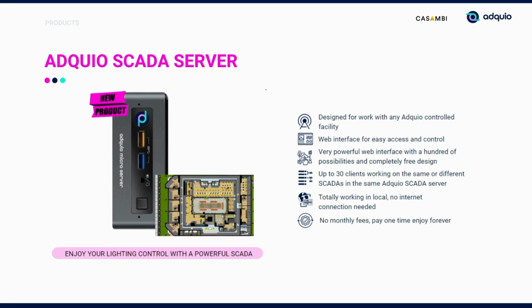You can use the pre-designed objects that the SCADA itself already incorporates, such as buttons and sliders, and connect them to the variables of your controller. And from the screen, you can then modify values in real time of your installation. In this way, we have two types of controls. One, to visualize the status of your installation, and another, to interact with it through controls within the SCADA itself.